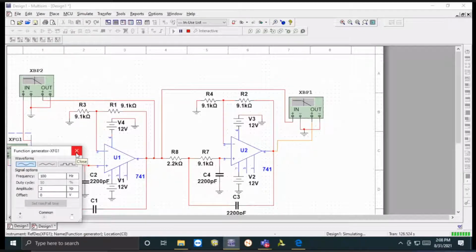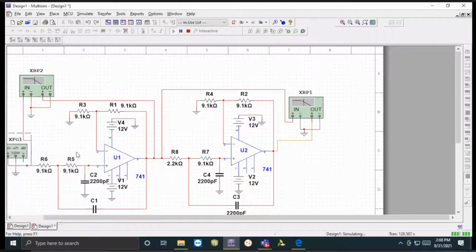You can apply a CRO also to see the nature of the signal, and the behavior of the signal at various stages, when it passes through the resistance, the capacitor, the filter that is going as input to the op amp, and then after passing through the op amp, where the amplification will be there. So all those things you should check definitely, right? And it will be better if you show all those diagrams, the step diagrams.